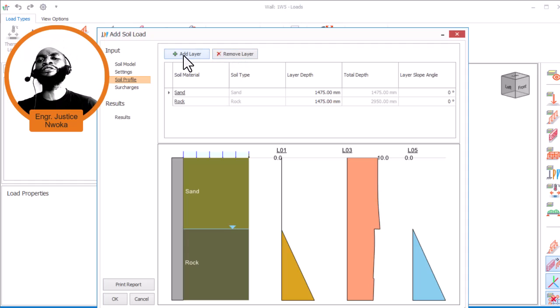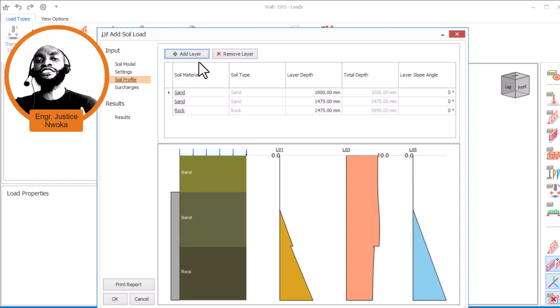And if you have any other kind of soil, like silty clay or clay, you can choose to come here and add that soil. If I go now, you can see that there is a different soil here. Can you see that we now have a number of soils. You can now choose to add your soil here. Click here and choose the type of soil. Just hold on, it will show the type of the soil layers right now.